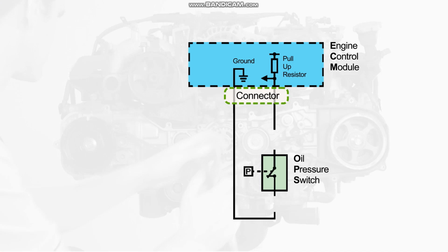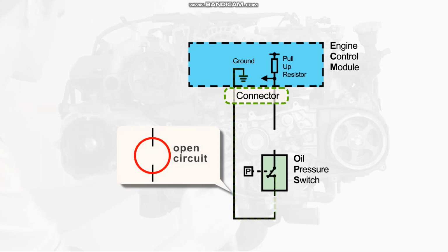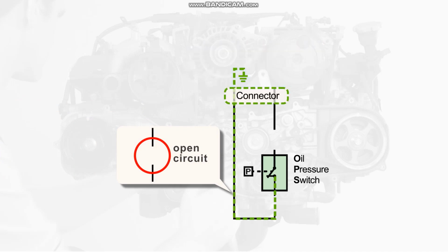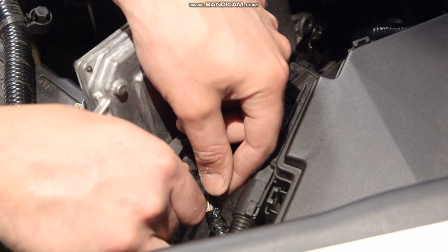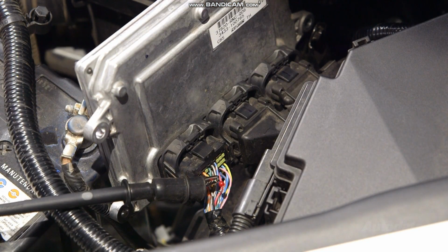If there was no ground or no short to voltage, there could be an open in the low reference circuit, module connector, or the module itself. If this were the case, the next test step would be to go to the next connector in line and check the low reference circuit, then recheck your readings. In this case, it would be the ECM connector.